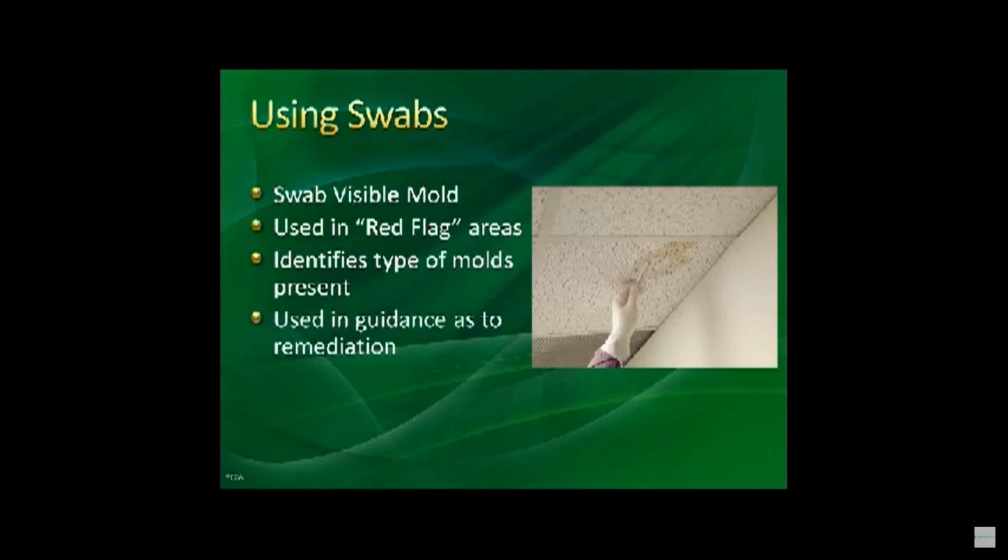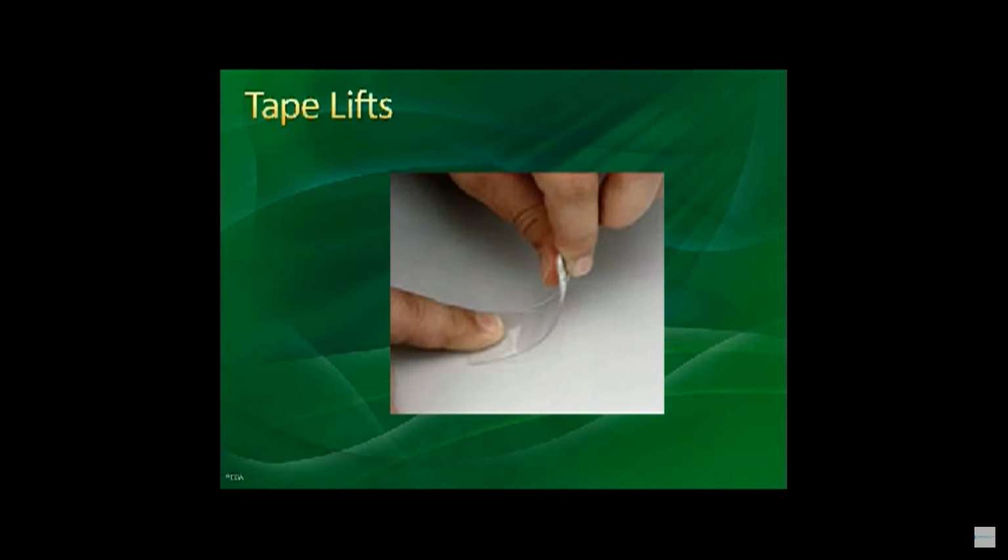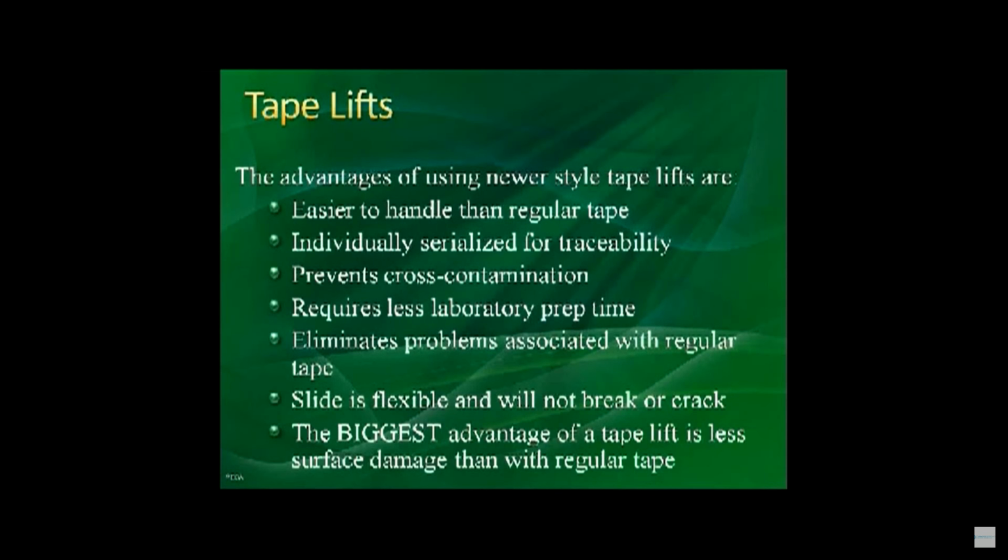Tape lifts are very simple. You press it over top of the mold or stain, and it has a predefined sticky substance. The advantage of these tape lifts is they don't cause damage. Regular tape will cause damage, so I strongly urge you to get the predefined tape lifts.